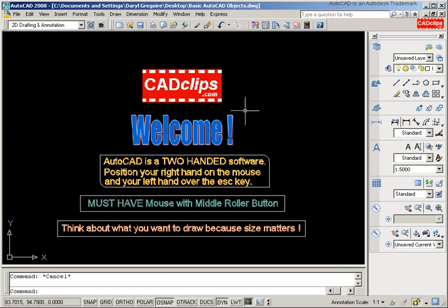Escape. We also have what is called a heads up control. If you type in a character like L for line, you'll notice it shows up over here. We can disable this, but I've started to use it and I really like it. And then you can hit a backspace and type in M for move. So you get this little command window that comes up. As soon as you type something on the keyboard, it immediately kind of freezes your cursor and then bumps you into this little window where you can type in a command, okay?